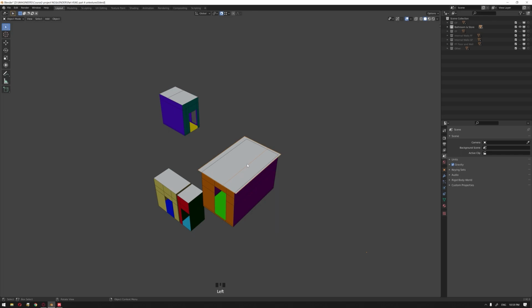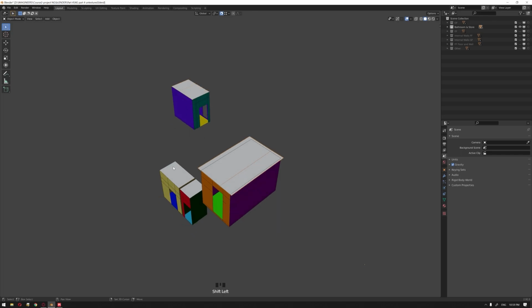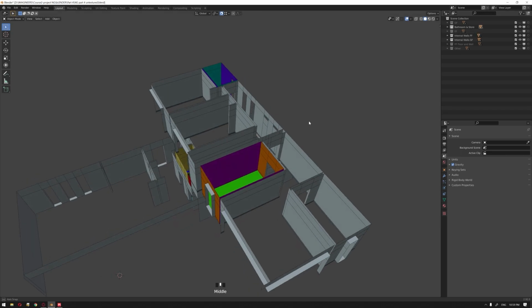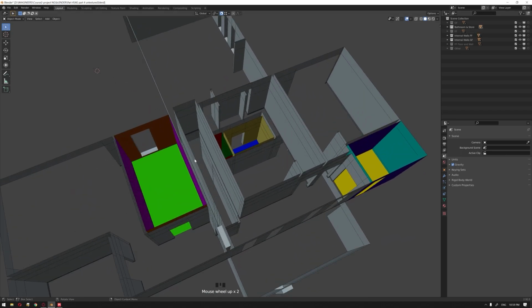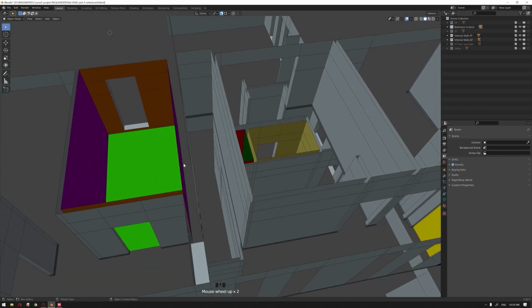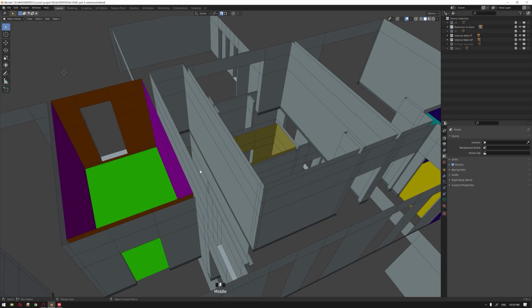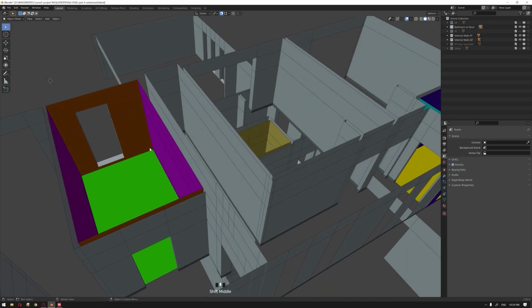To start, just to give you an idea of what we did, basically we have removed all the invisible faces that were available during the modeling process. So more specifically, all of the upper and the bottom part of these walls have been removed, so we can actually minimize the amount of these faces and give more space to the other faces and the unwrap texture layout.